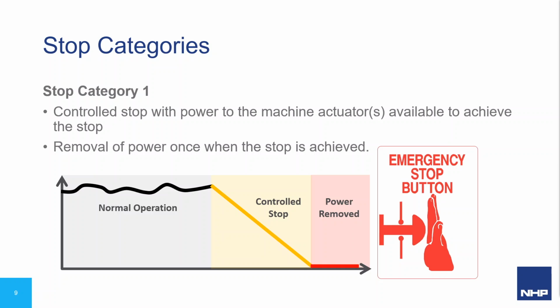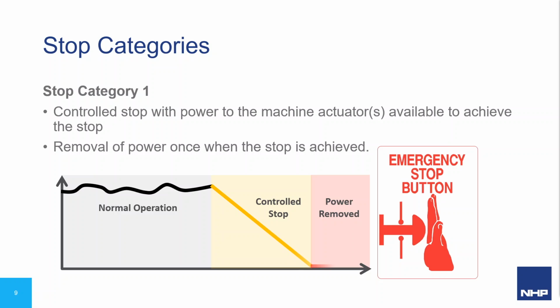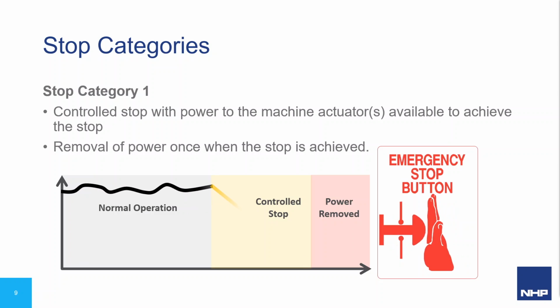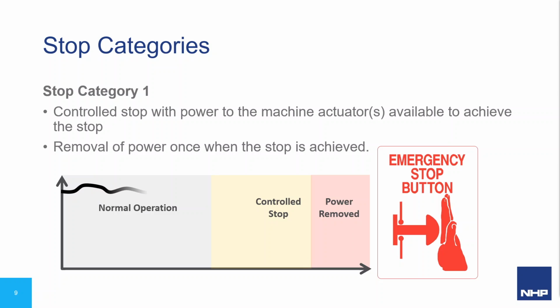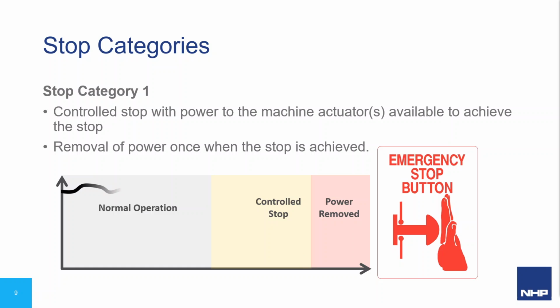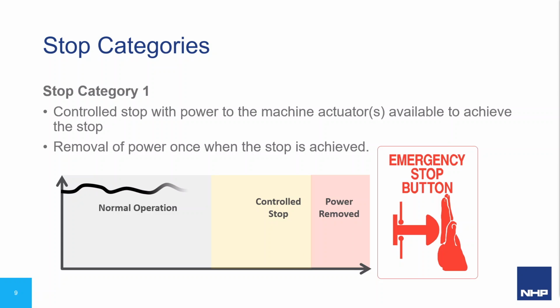This type of controlled stop is often used with variable speed drives or variable frequency drives, which permit ramping down or dynamic braking. Once the ramp down has run its course, the drive is shut down safely. The reaction times are reduced compared with allowing the motor to coast down. As a result, in many cases, the safety distances to the hazard can also be reduced. This provides a number of benefits such as improved ergonomics for the plant operator, space savings due to the reduced distance between guards and the hazard, and of course cost savings. Let's have a look at an example of both stop category 0 and 1 circuits using safety monitoring relays.